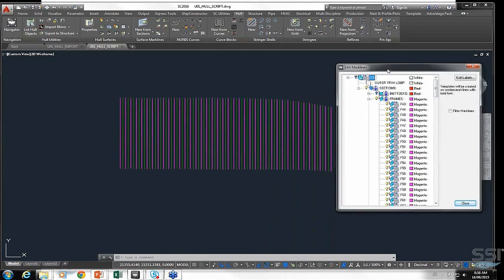I just want to mention at this point the value of this Mark Line Properties box. You can see how quickly we can manipulate the mark lines and the surfaces themselves, how we can use this information to create NURBS curves. And I'll actually quickly just highlight for a second, earlier on, I'd mentioned that we auto-created the forming templates. It's here. If you were to select one and say toggle as template, this is how you could use one of these mark lines to create your forming templates as well. So it's a very valuable window. Definitely spend some time playing inside of there.